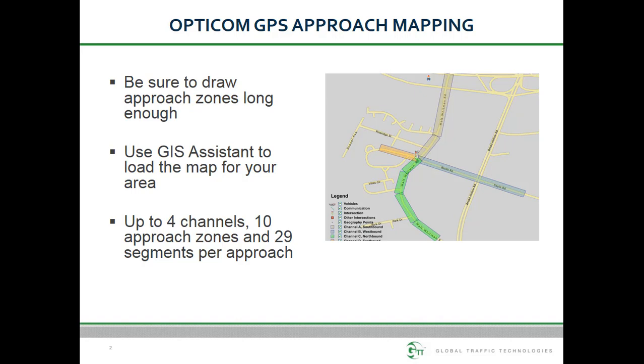It is not recommended that the length of the zone be used to determine the triggering point for TSP or EVP calls. Once in the zone, the ETA and distance thresholds programmed within the on-site configuration profile section determine when the call is actually made. The range setting video goes into more detail for setting triggering thresholds.